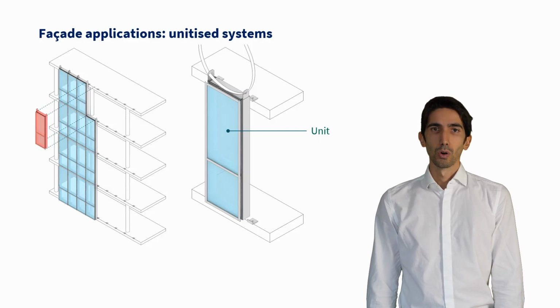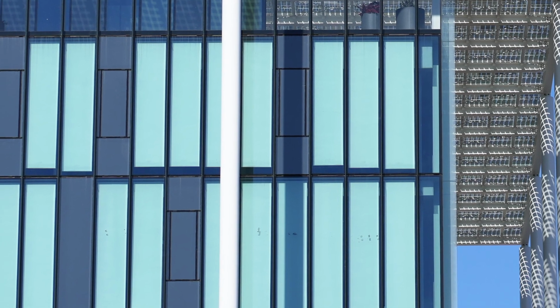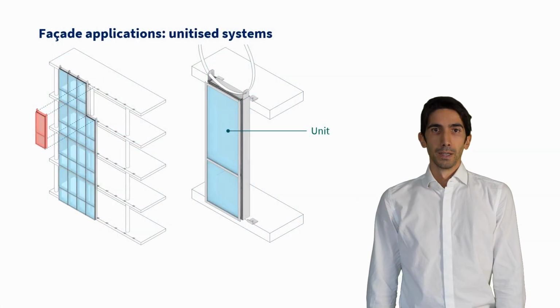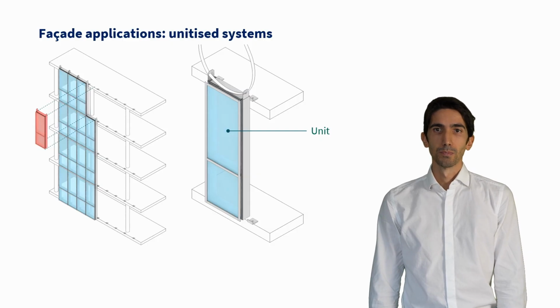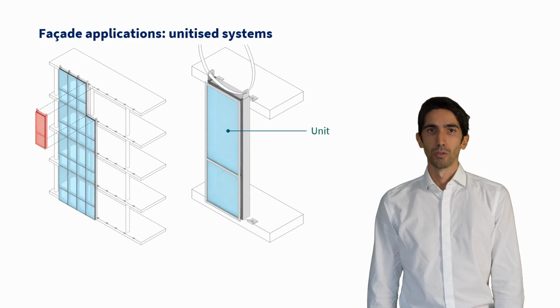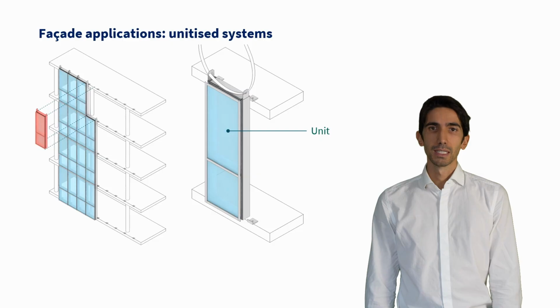This approach allows also, when required, to use the structural sealants to connect the glass to the frame, avoiding the mechanical fixing and the following cover caps, resulting in a fully glazed effect. The facade is composed placing each module side by side thanks to additional external gaskets that assure the air and water tightness between the modules of the envelope. Considering that each module is complete and does not require any additional work, these facades can be mounted from the inside without any external scaffolding.